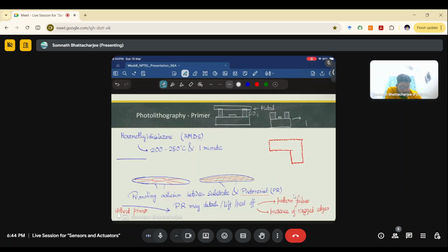In the next one, first you have to prepare a sacrificial layer. So in between these, you need to have a sacrificial layer, and this is completely your sacrificial layer, which you will remove afterwards, not right now.